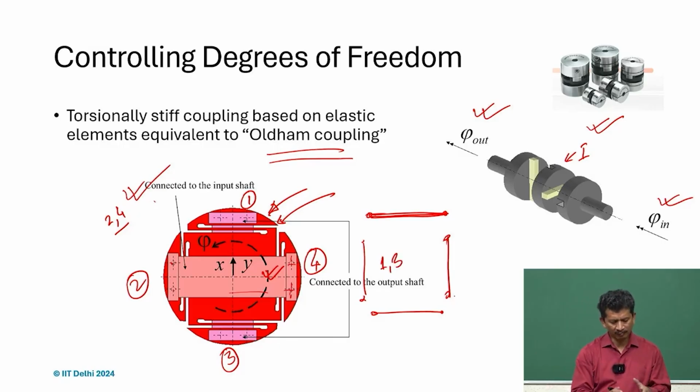So the coupling here is just a thin plate. You just take a very thin plate and make this structure. So you just remove the material. If you really want a very rough one, you can even use a saw and just make those slits, and what is important is this functional part in the center, a beam-like structure.